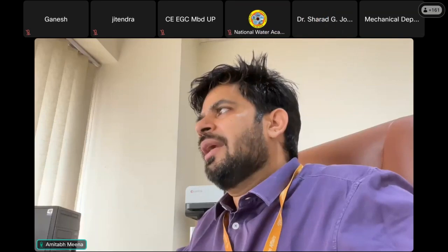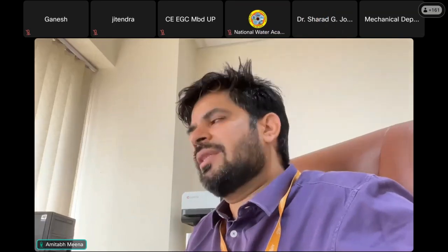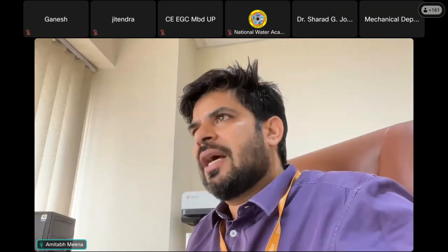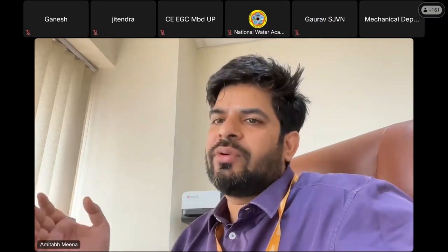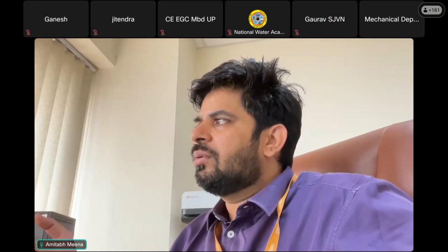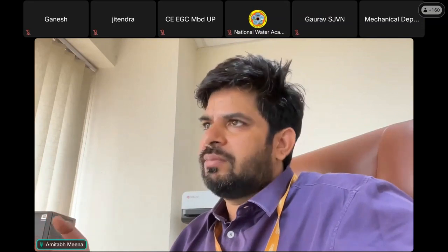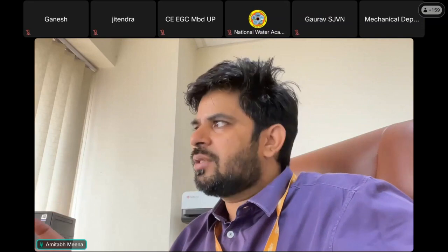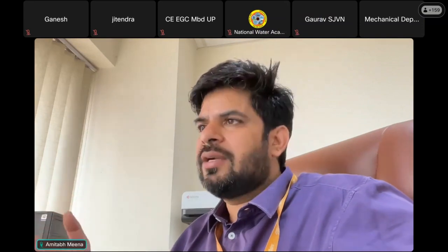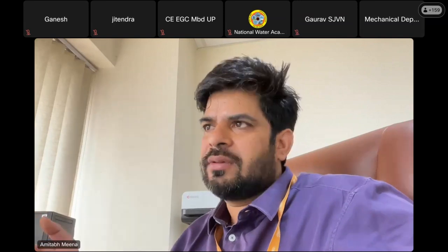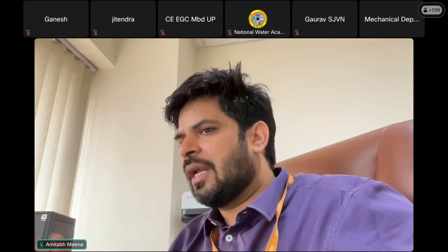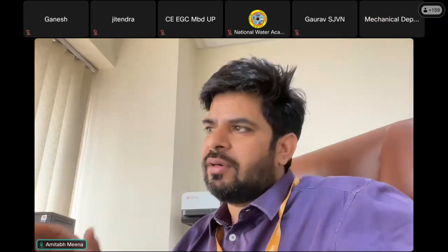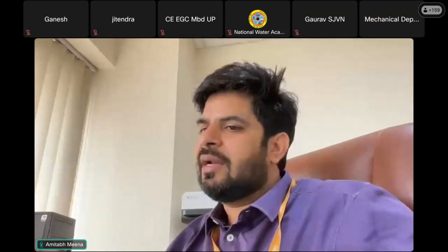No, for categorization, the criteria is the same. If the responses to some questions are poor or critical, then it goes to category 1 or 2. It doesn't depend on the structure. It depends on the responses to the questions, whether it's a dam or barrage. Actually there are separate questions for barrage. Some questions are common for all, some are different for concrete dams, different for embankment dams, and different for barrages.